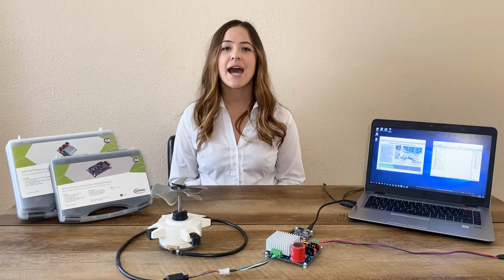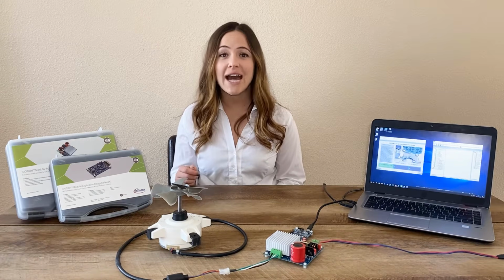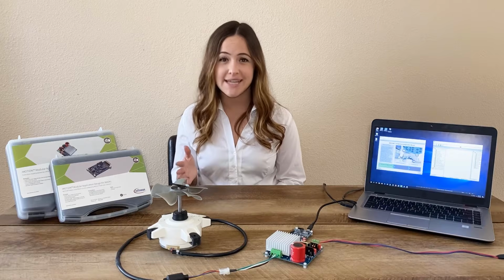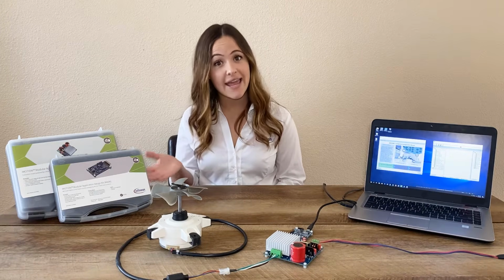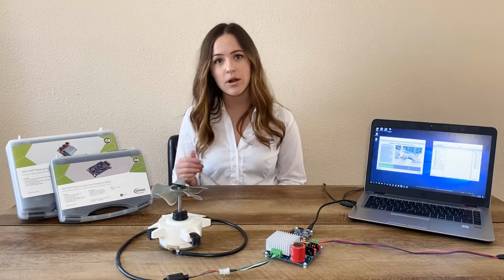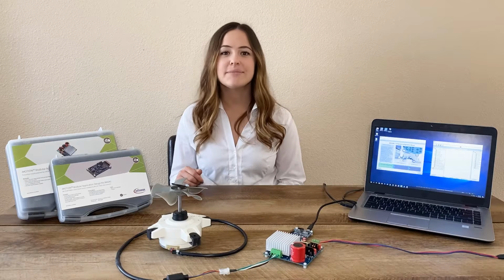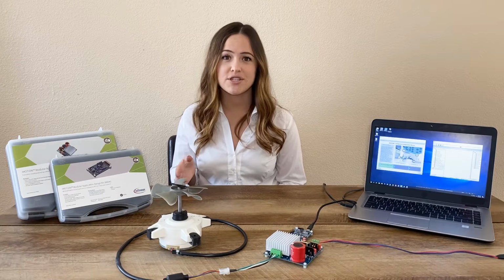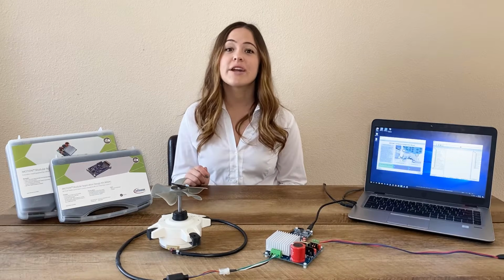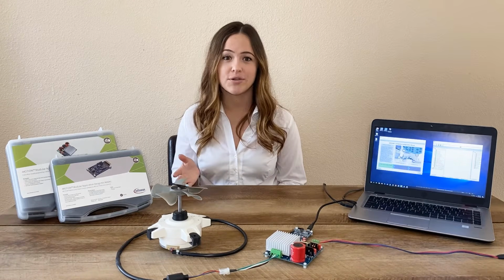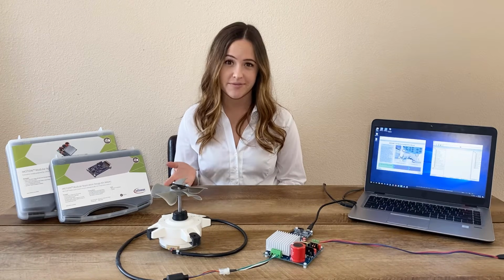iMOTION 2.0 tools and devices. iMOTION 2.0, which I'll simply refer to as iMOTION from here on out, is a highly integrated solution platform that is dedicated to motor control. iMOTION products come with Infineon's patented and field-proven advanced sensorless or Hall sensor-based field-oriented control algorithm. This algorithm is implemented in a professional motor control engine, which we simply refer to as MCE, that eliminates the need for users to write complicated motor control algorithm code, and also helps reduce the time to market for variable speed motor drive product development.